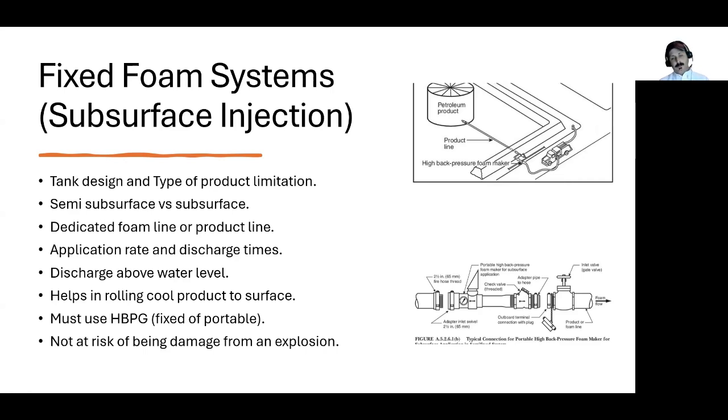This will help in many ways. It will circulate the product inside and prevent the formation of a hot product layer. And I did mention this situation happening in crude oil tanks that will cause an ugly event that is called the boil over. You can check it in the other videos on my channel.